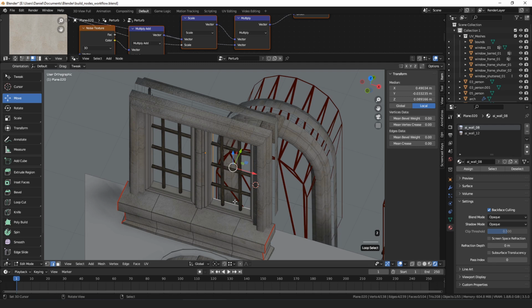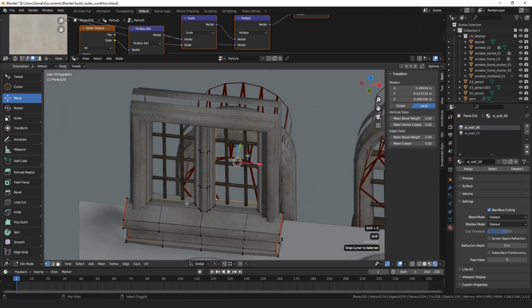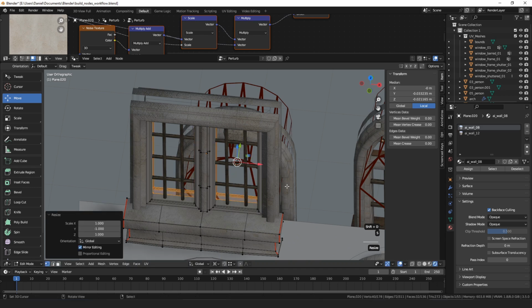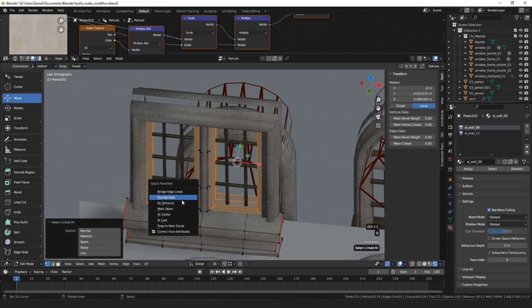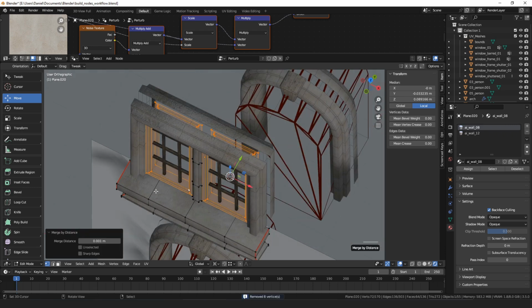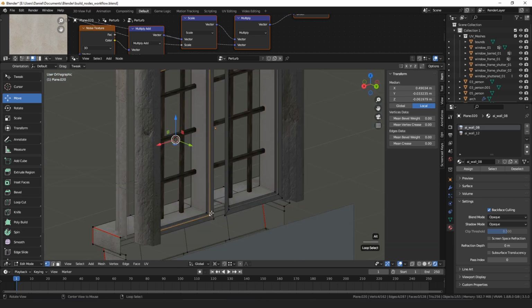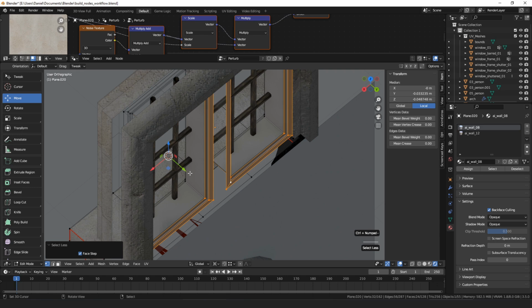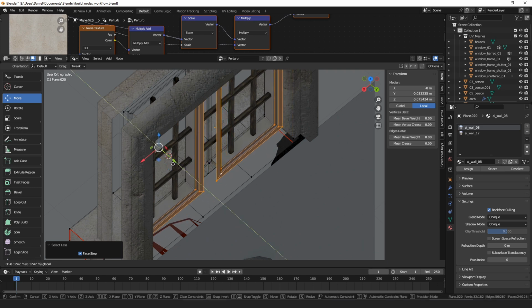So the way we'll do that is we can just select this edge loop, snap the cursor to it, select everything, pivot around the 3D cursor, make a copy, scale it on Y by -1, fix the normals, select everything again, remove the doubles, or merge by distance, select this center loop because we don't really need it, delete edge loops, and then we can select one of these outside loops, use Control Numpad Plus to grow the selection till we have the back half selected. And then we can adjust it to be whatever size we desire.